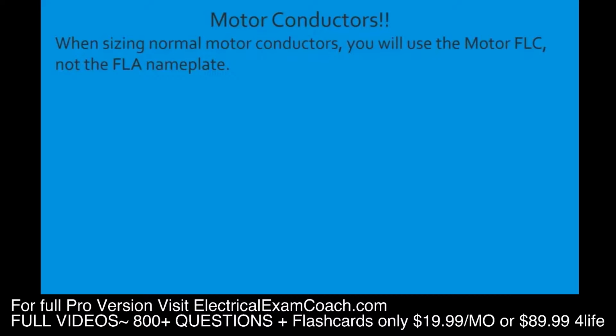The FLA nameplate rating is typically the amperage value that they've stamped on the motor's nameplate. Remember how we've learned previously that every piece of equipment has a nameplate, and it'll say things like what voltage the equipment is and what the amperage is. Well, on motors, they'll typically stamp an amperage, but that's the FLA. So when we're sizing normal motor conductors, we're actually going to use the FLC, and I'm getting ready to teach you how to find that value.